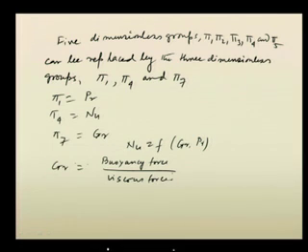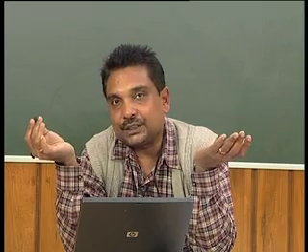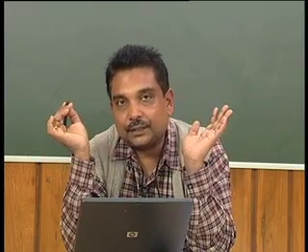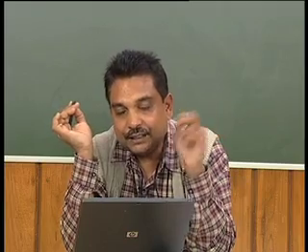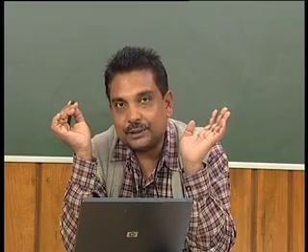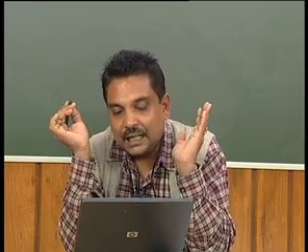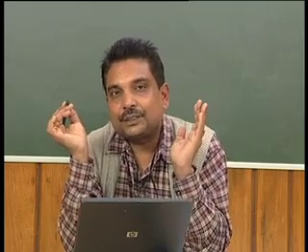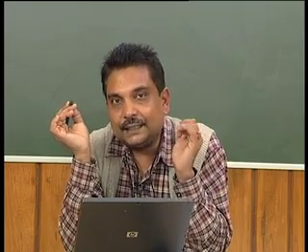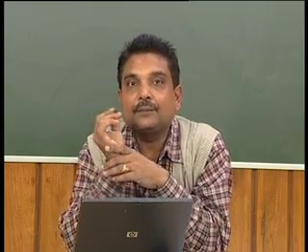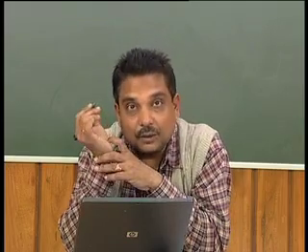So, this Grashof number, if we try to compare between the forced convection case and the natural convection or free convection case, we have seen that in both the cases there are Nusselt number terms, there are Prandtl number terms, and in case of forced convection there was a term that is called Reynolds number, and here that is being replaced by another terminology that is called Grashof number.